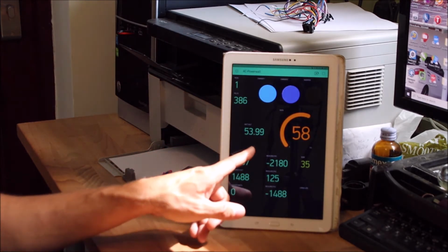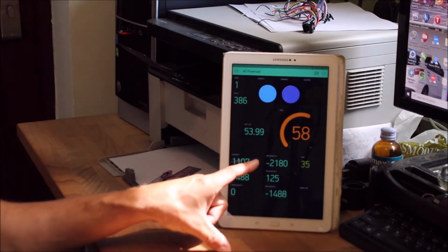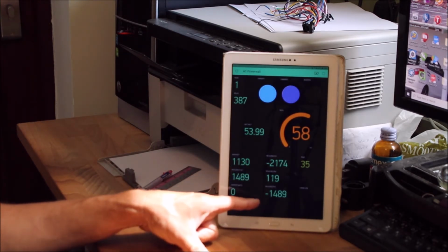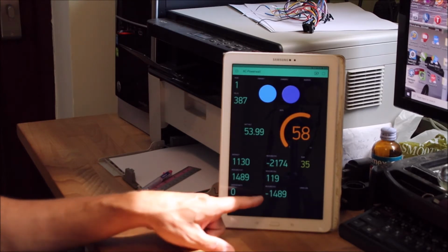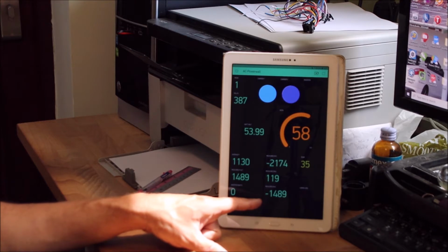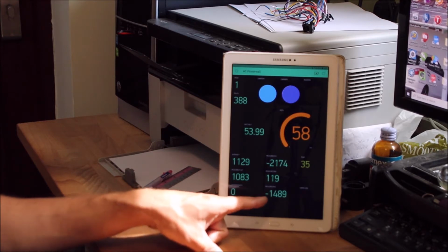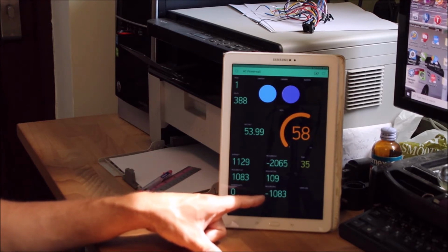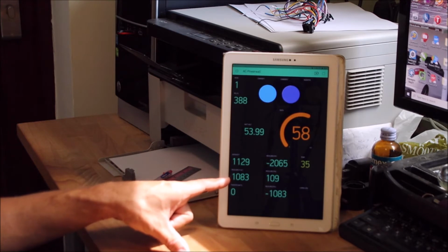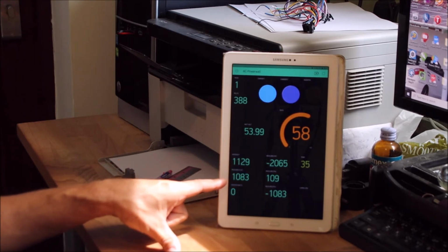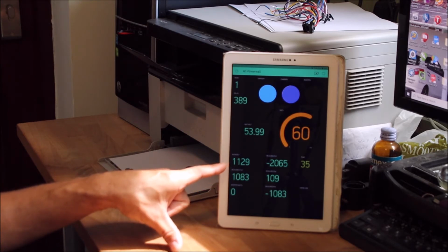And here in the middle part, this is phase 1, phase 2, phase 3 readout from the smart meter. And then I told the Powerwall which one is the active phase, and in my case it's phase number 3, and this one it takes over here for doing its internal calculations for the average power in the last cycle.